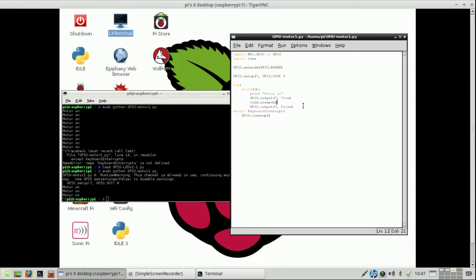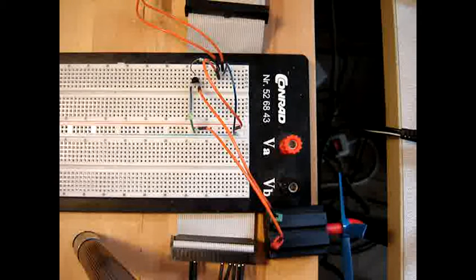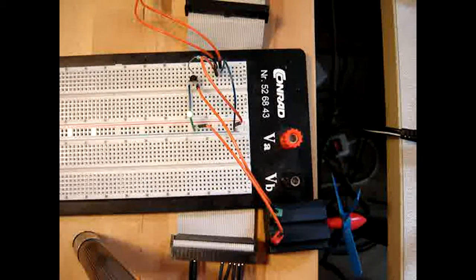However, the motor is not running, and let me show you on camera. So with the code I will show you what happens. The LED clearly is burning, but the motor doesn't give a sign of life, and that is clearly what should not happen. So just maybe the 3.3 volts is not enough, but we'll have to check whatever happens. So to see if this really is the case, I have to measure the voltage.